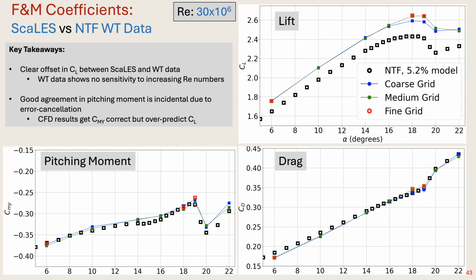So, the idea for why we are overpredicting CL, definitely there might be a situation in the CFD modeling where there is something we don't model that's happening in the tunnel. And that could be, like, we are doing a stiff geometry, maybe for this high speed case the wind tunnel test article deformed a little bit, and it's seeing 0.5 to 1 degree less angle of attack. That could be one reason, but until it's verified, we don't know.